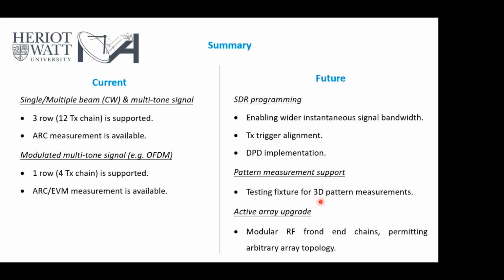In the future, we're trying to align the trigger so that we'll be able to have more chains supported for the modulated multi-tone signal. We're also trying to implement DPD on the SDR platform. Also, we're pushing to design the pattern measurement feature for fabrication. And we are thinking of the next active array version as well, to add more flexibility.